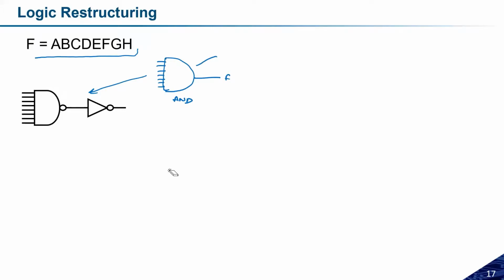To speed up the circuit, sir. Speed up the circuit, but the important thing is, how will we speed up the circuit? Sir, TPLH in an AND gate is proportional to the fan-in factor, but in NAND it is not. Okay. Anyone? Anything else?